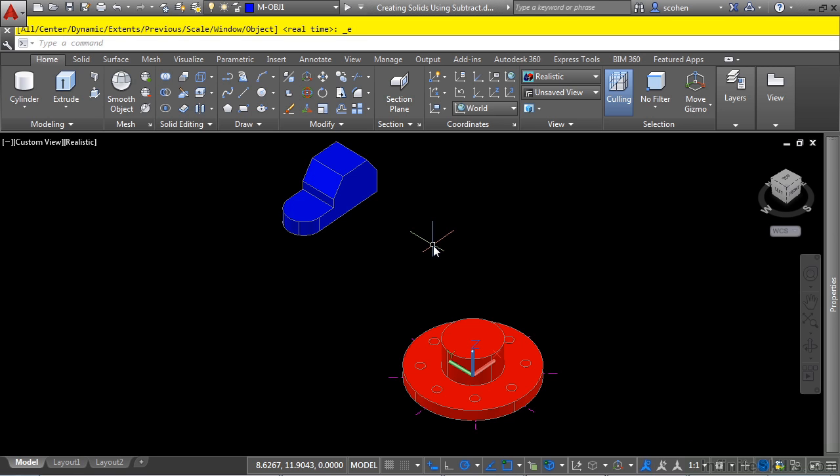Upon completion of the command, the first set of selected solids are unioned together, and then the second set of solids are subtracted from the first set. All the selected solid models are consumed into that new composite solid. The solids that were subtracted from the first set are no longer available for future Boolean operations. Let's draw some objects that we will use to subtract out to complete our solid models.